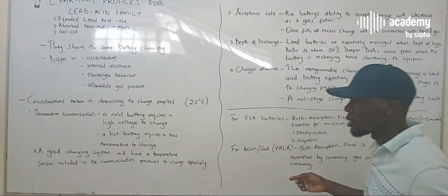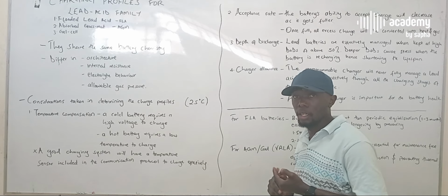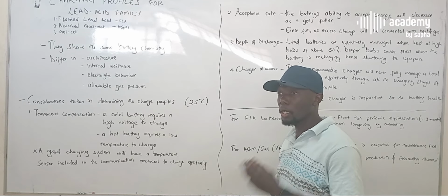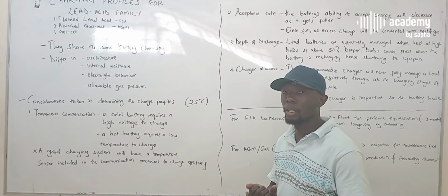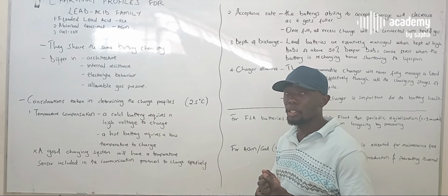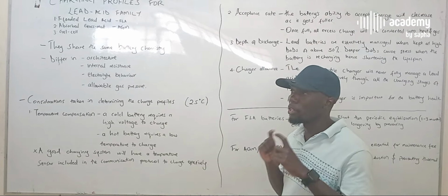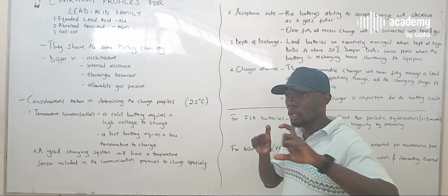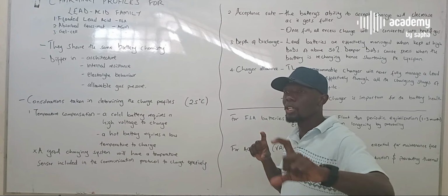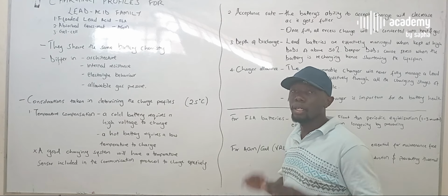This statement means that if your charge controller does not have inbuilt programs, or it's locked and can't allow you to add any extra programs in the charging profile to manage the charging stages, your charge controller basically will just keep this battery in one particular charge stage for its entire lifetime. And we've explained that when your battery is kept at that single stage in its entire lifetime, the lifespan is lowered.